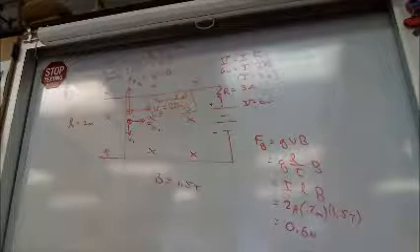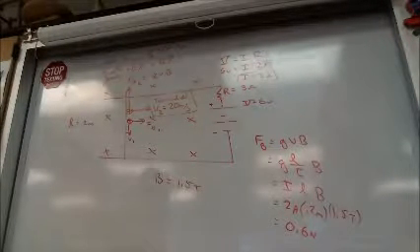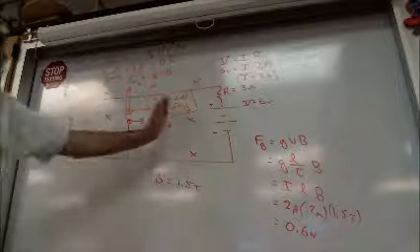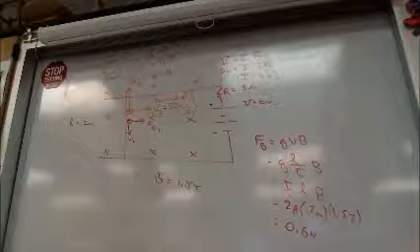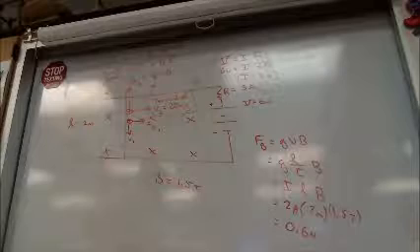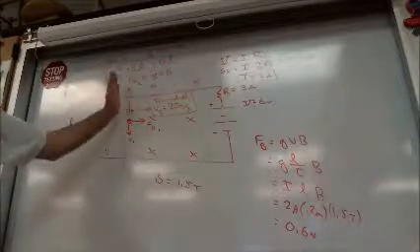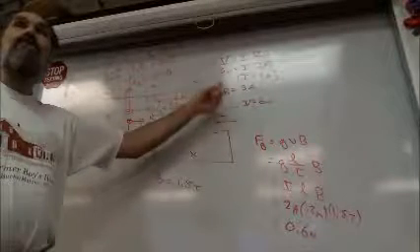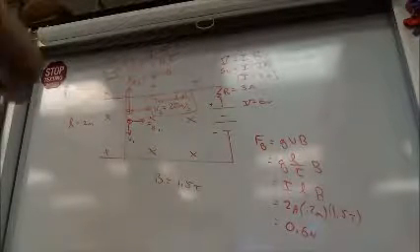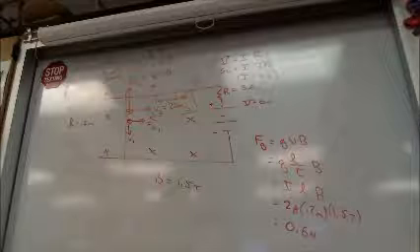At terminal velocity, what's our current? Once we reach terminal velocity, do you have any idea what my current would be? Yeah, 2 amps. Try again. 0. Oh, okay, sorry. Because when I'm at terminal velocity, the voltage going backwards is equal to the voltage going forwards. So the current, boom, cancels. Nothing's happening. Gotcha. I think this is very interesting.